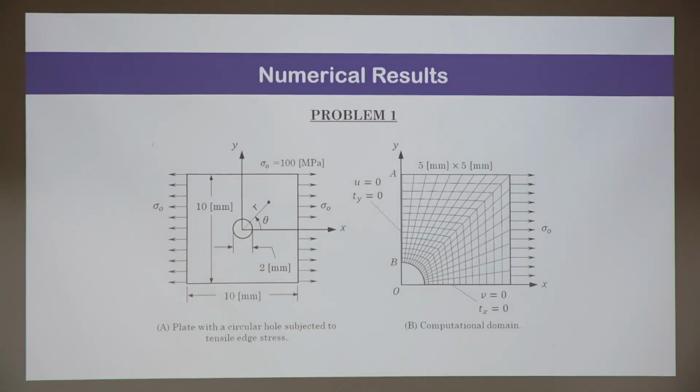a very, very powerful technique came out of the marriage of these two. And so in summary, I must say the marriage is to borrow the concept of finite control volume. Okay, no weighted integral statement. Take the balance equation directly, and it converts the domain integral into a boundary integral.